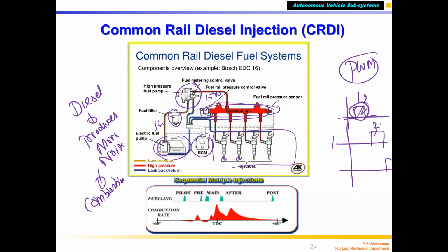If the combustion happens in a diesel engine, it is more compared to petrol. Petrol easily evaporates because the combustion happens as the fuel is evaporating. You are injecting fuel inside the diesel engine, it evaporates and burns. Because of that only, the combustion noise happens. That's why a diesel engine always makes more noise compared to a petrol engine, which cannot be avoided. Combustion noise is high.